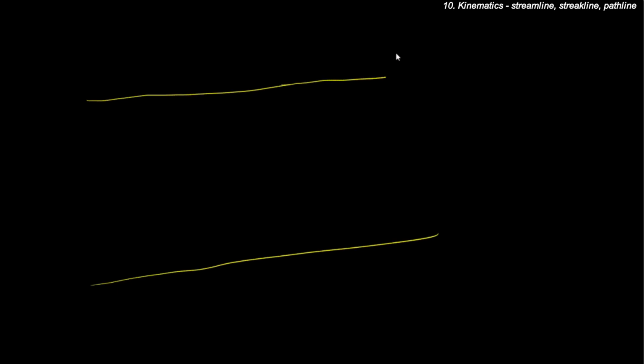Let us magnify the drawing and try to arrive at an easier viewpoint. Suppose this is the domain and this is the needle of the injection. At t equal to 0 seconds, a dye particle comes out like this and the flow is in this direction. At t equal to 1 second, the red dye particle will arrive at this particular point, but another dye particle will be injected into the domain.